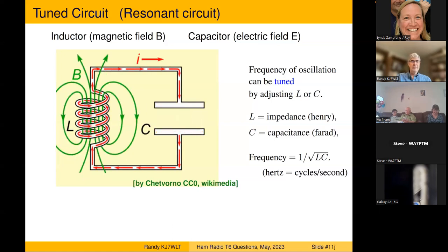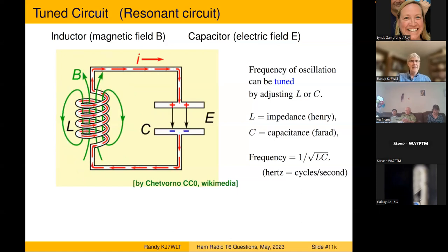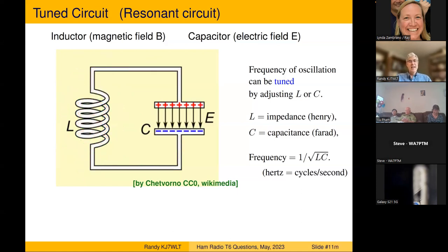Again, it gets converted into magnetic energy, like the pendulum being at the bottom, and it's all kinetic energy. And then it goes back the other side and gets back to exactly where we started. And in an ideal world, that could keep going forever. But just like in a swing, there's resistance. Some energy is being taken out of the system by the resistance of the electrical wire. And so if you want it to keep oscillating forever, you have to keep putting a little bit of energy in.